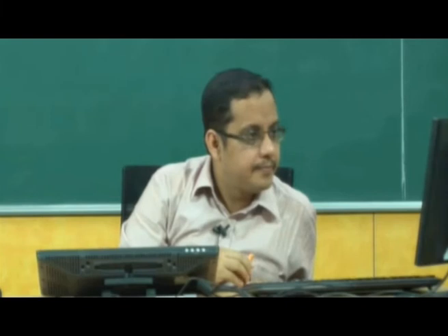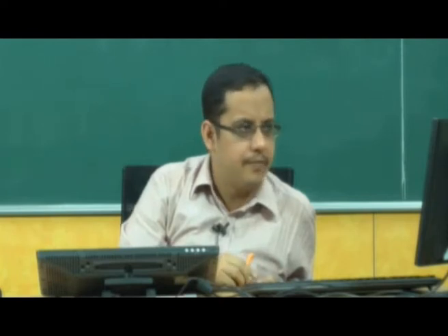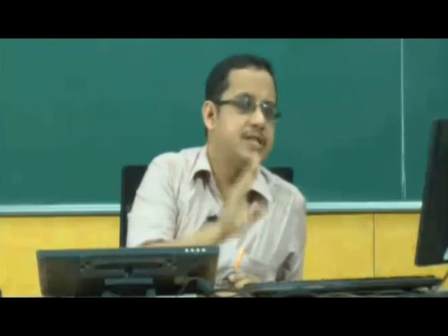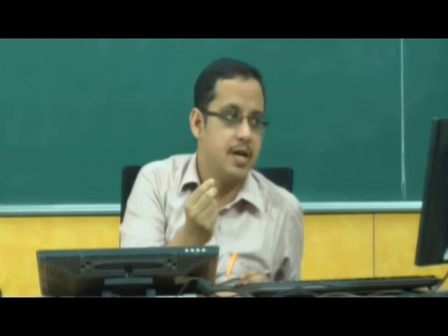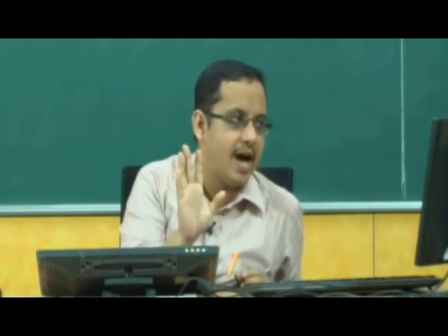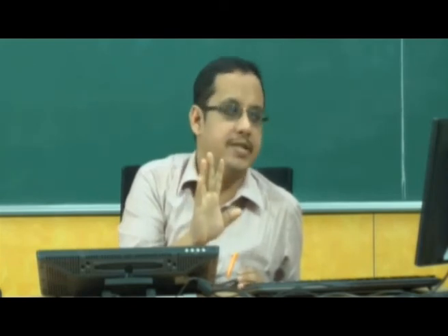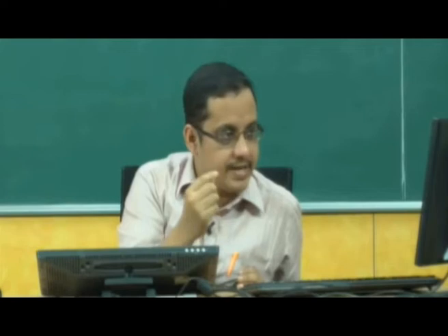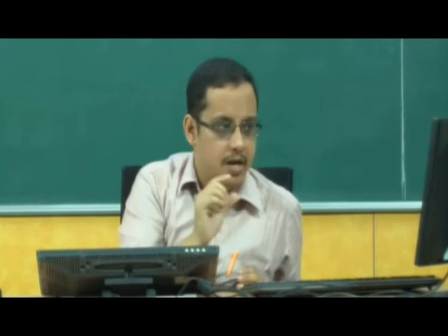You have talked about the detection of single plane unbalancing. We find that the unbalanced mass is just below the point of rotation. But how can we find the distance? No, we cannot find the distance directly. We are just detecting. Detection does not mean that you are actually finding the magnitude of unbalance. You are just detecting that there is a single plane unbalance problem, a static unbalance problem, associated with this machine. That's all. How to estimate the unbalance, there are separate experimental procedures for it, but the title of the